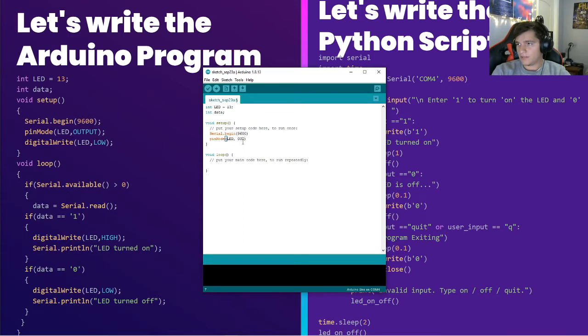So here we're telling the Arduino which pin to use. We have to in order for the Arduino to communicate those signals to that specific pin. And then we're doing a digital write. And since the LED is either a 1 or a 0, which is the low and the high, we're telling it to turn on or turn off. So now we initialize that.